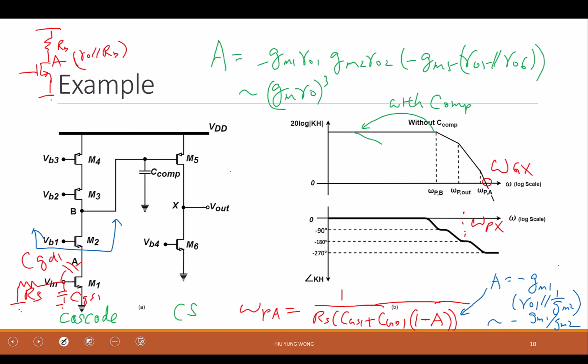And then what will you do? I need to draw it in the right way, so let me move even more, in case my drawing is not good. Right, so I start from here. And then I'm going to have a parallel line going down. Do you see that? And then when I hit the second one, I will go down faster. Right, this is the second pole. So now my gain crossover frequency, I moved too much, of course it's not necessary, but just good for my drawing. Gain crossover frequency is here, right?